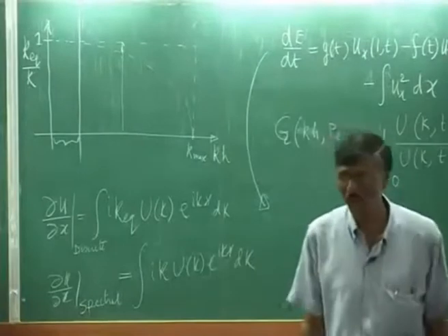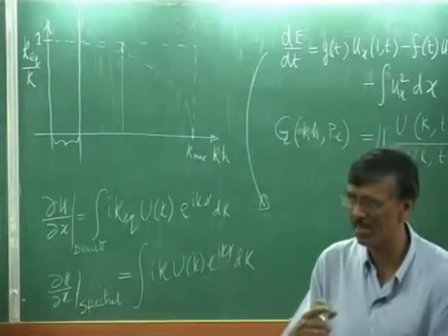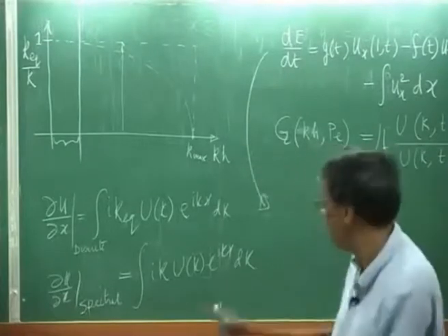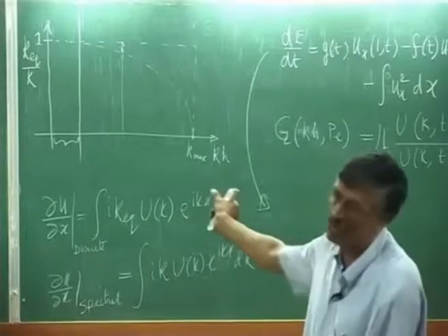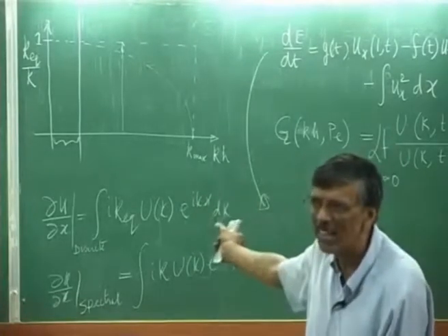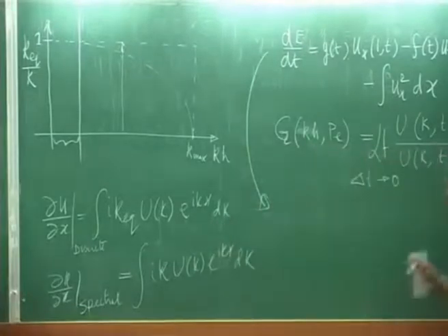This is the second step. So, the first step is choosing the spacing that fixes the Nyquist limit. Then the second step is choosing the discretization method that tells me which is really the usable range, the rest of it is basically collecting garbage, accumulating error. So, those results are not trustworthy, one should not be taking them seriously, although most of the time people do that.